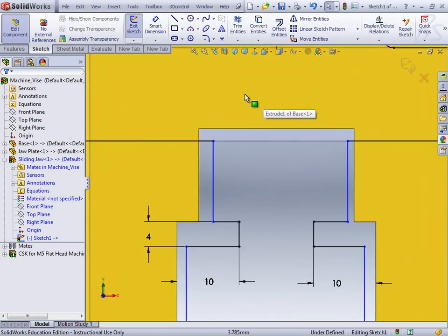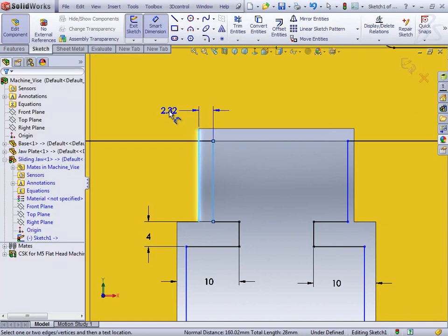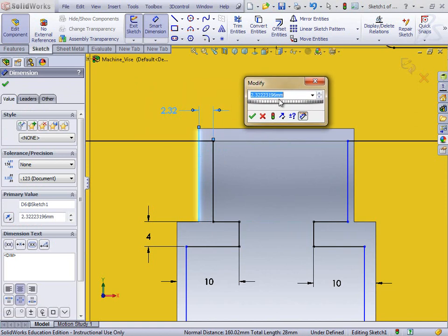So to link a value, and this is going to come up in the test, so this is one that's going to be facing you. If I go in and throw in an ordinary dimension as you would normally, instead of just typing in 1 and accepting, I type in the 1, and also click on the little drop down arrow here, and select this little link value option.